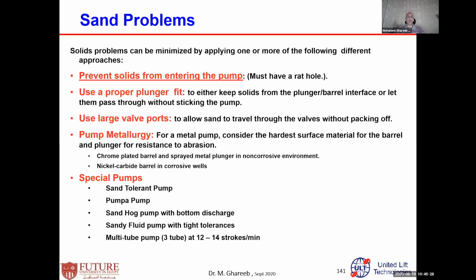Try to use a large valve bore. It's not always true in this condition, but it requires some expert to design, depending on what size of sand, the volume of sand, and what type of sand. Metallurgy, because the metallurgy is very effective with the friction, special types of pump, and so on.